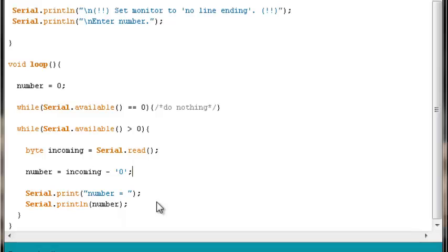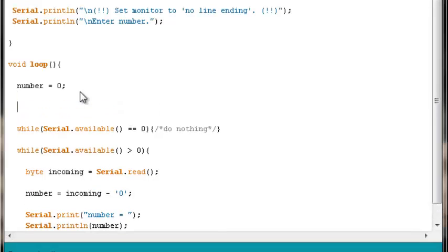Now, as it sits, this isn't the best practices way to do this. For one thing, we could add things to this piece of code and make it better. One thing we could do for sure that, with a single digit, doesn't really make a lot of sense. But once we start pushing multi-digit numbers, it's always kind of helpful to make sure that that buffer is completely empty by the time we get to this point, because we don't want some byte of data still hanging out in that receive buffer, because it'll immediately kick it through here. And we want it to be 0 and pause long enough for us to enter a multi-digit number, and then it read that particular number, not whatever trash values are in the receive.